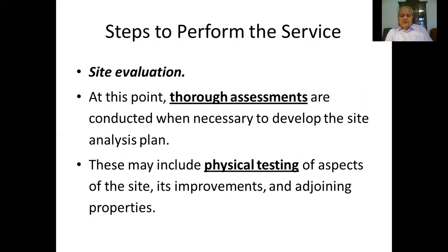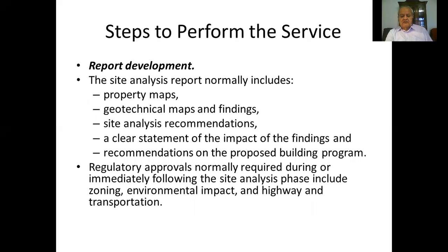So the site evaluation is done through assessment that includes all the physical testing of the soil, of the conditions, of the materials, and so forth. So you write a report at the end of the site analysis that has the property maps, geotechnical maps, site analysis recommendations, a statement about the impact of the findings, and recommendations for the proposed building program.